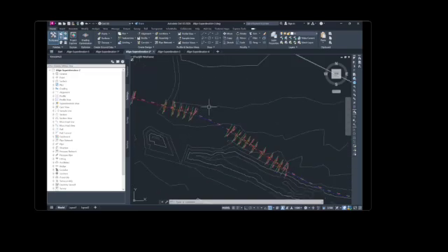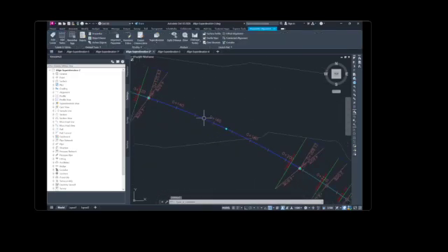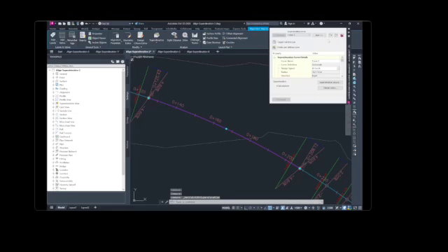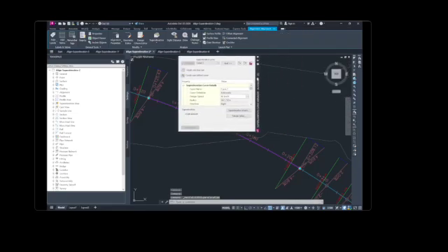Select the alignment. Click Alignment tab, Modify panel, Superelevation drop-down, Edit Superelevation. Under Superelevation Curve, click Next twice. The window displays the parameters for the third curve, which is highlighted in the drawing.